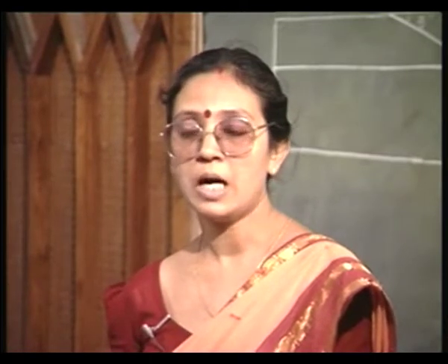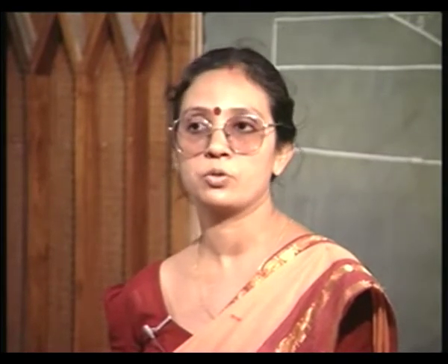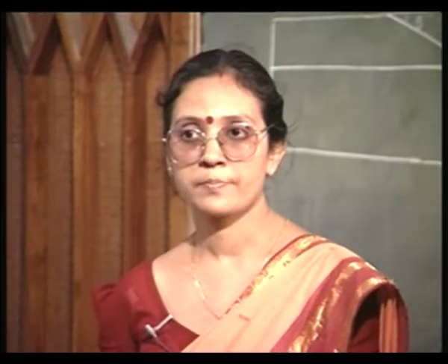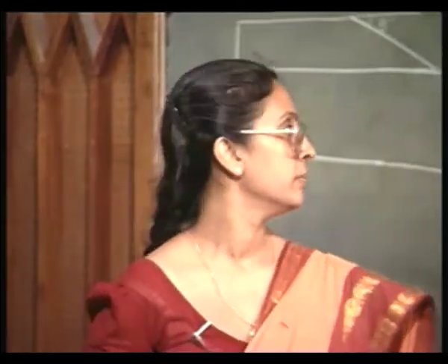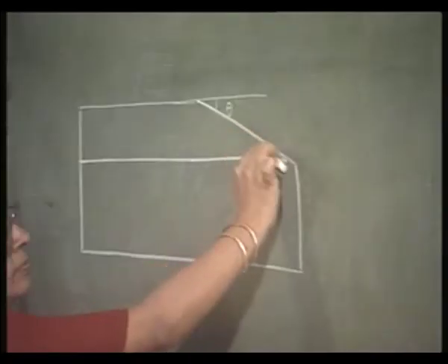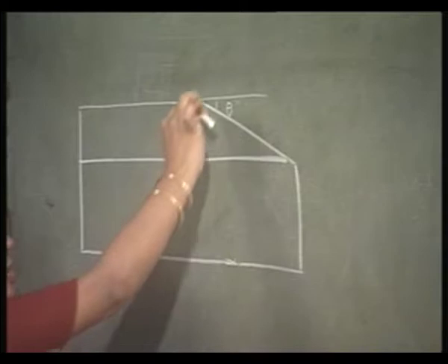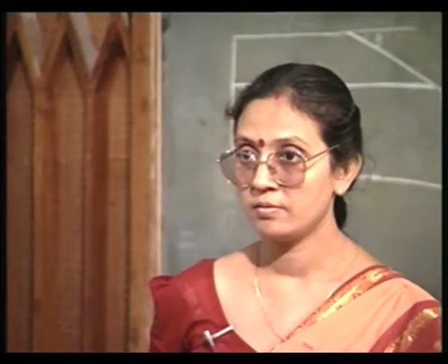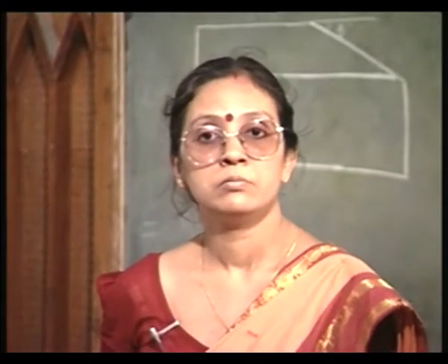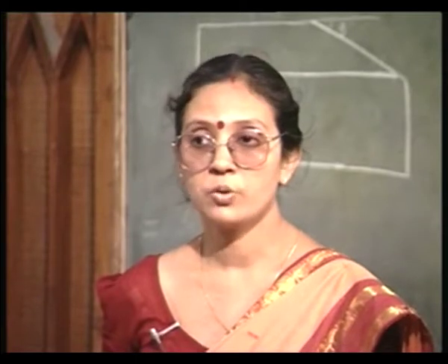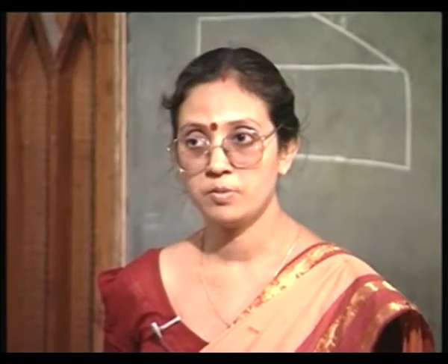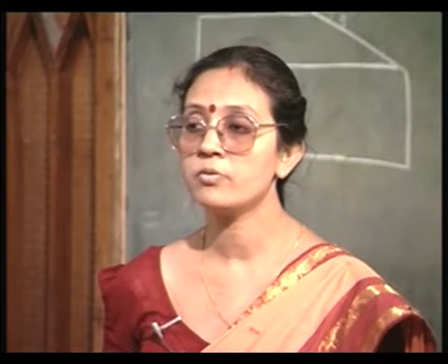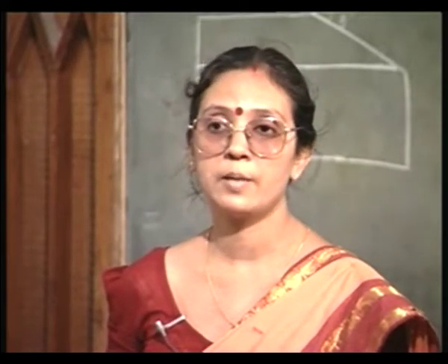Now, if you view it under the microscope, you can measure this. This is the P region. This will be stained in preference. So, you can measure the stained region and you know the angle theta, so you can find out what the junction depth is going to be. It is a very common way of measuring the junction depth by angle lapping and staining.